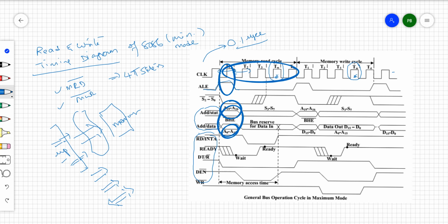Whatever bit combination is on those 20 pins coming out from the processor is acting like an address. That address is used to select the chip as well as a particular location in the memory. Once the location is selected, the read control signal, which up to that time is high, goes low. Once it is low, data is read from the selected location onto the data bus. Through the data bus it is read into the processor. The control signal here is the memory read control signal. Through the data bus, data is now being read into the processor.